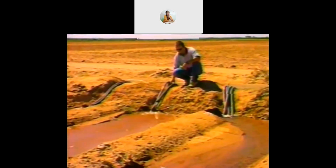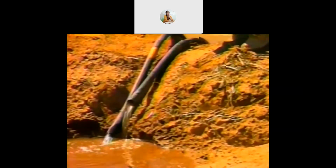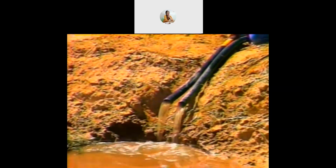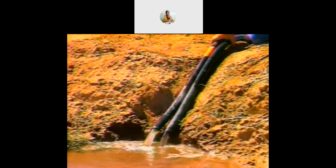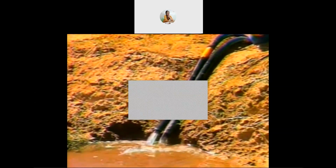By raising or lowering the end of the siphon tube, you can equalize the flow between all of the furrows, or give some furrows more or less water as needed. If runoff isn't a concern, increasing the flow rate and shortening the set time will reduce the amount of water wasted, but there are limits. Too much flow will cause scouring and may break out berms and furrows.